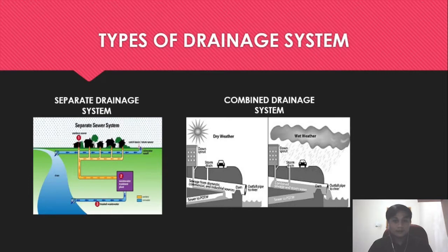Some or all of the stormwater is channeled into the wastewater drainage system. Surface water as well as foul water will be dumped into the sewerage treatment facility. It may be possible to extract some foul water at various places in the drainage network to avoid overloading the treatment facility. If the surface water is less thick than the dirty water and flows to the top of the drain, this can be accomplished. Surface water can be diverted into a stormwater channel or drained using a separating device.